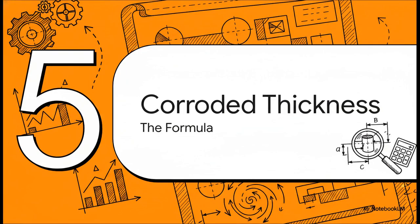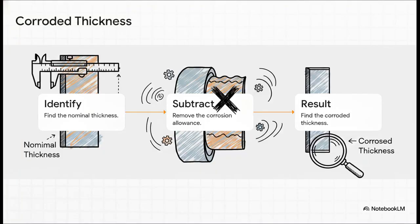So how do we actually use this? Section 5, the corroded thickness formula. Here is how this plugs into the critical math you'll be doing every single day. If you want to know how much steel you'll actually have left after years of harsh plant operation, you start with your real-world nominal thickness. Then you subtract the corrosion allowance you expect over time. And boom! That gives you your final corroded thickness. It's a simple step, but it's absolutely crucial.